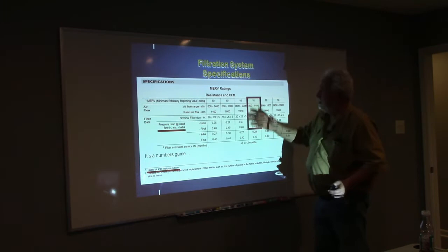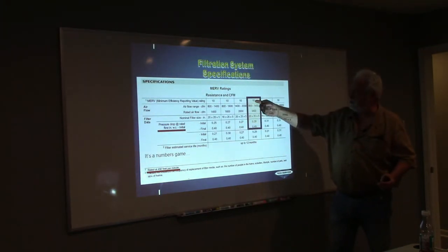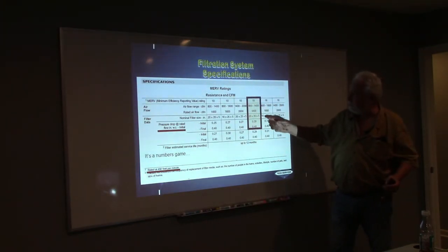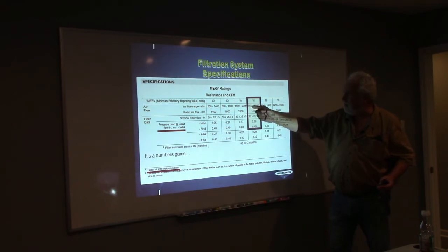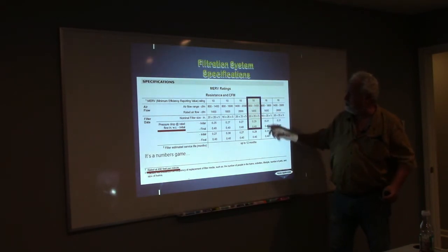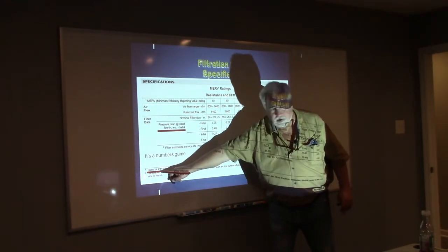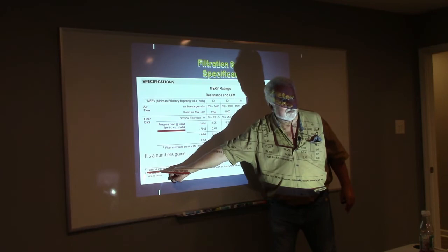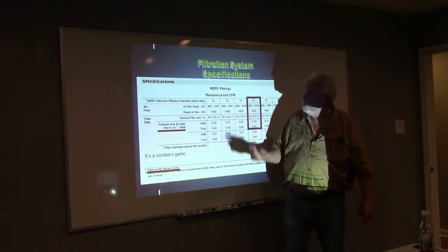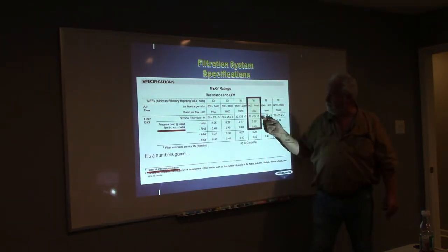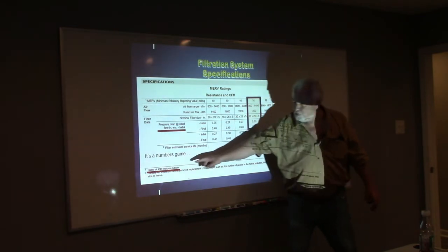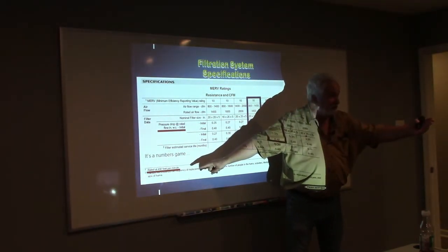So, look at this. It says this MERV rating filter, this 16 MERV rated filter, it's designed for airflow at 800 to 1400. They rated it at 1400. The pressure drop on there is 0.29, which is crazy. But look at what it's rated at. 492 feet a minute. Good. So all of your extended pleated filters, that 5-inch filter, they're rated at 500 feet per minute.